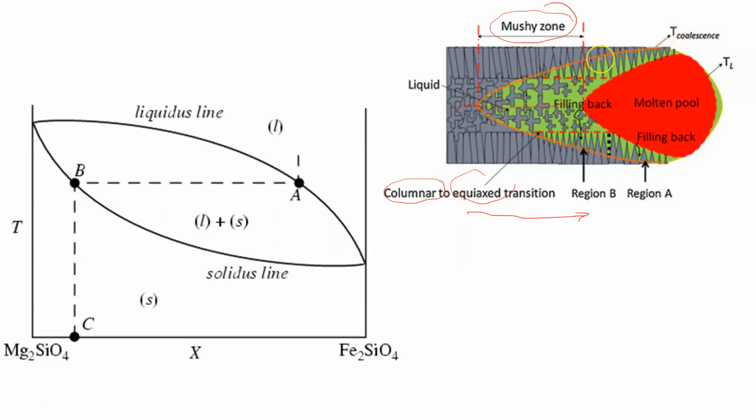And then as you travel away from the material, in these directions here, is the effect that you're having on the base metal, beyond just where the weld joint is taking place. And that's what's known as the heat affected zone. That's the material that might not be brought up to the molten state. It may still be in this recrystallization state, simply because the temperature is dropping the further away you get from this source of heat, and then further into the solid state. So you've got this entire zone of material that's going to be affected by the heat, but it wasn't necessarily the target of the weld.